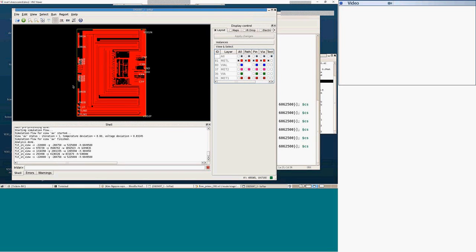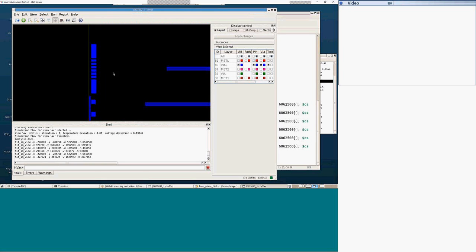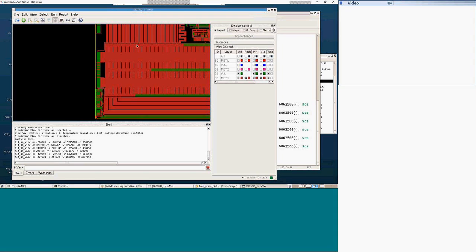So that's what we have, and this is GNDB. GNDB is fully disconnected, so this is a disconnected segment. It has only vias to metal 2. L2 is also disconnected, and it obviously has vias to metal 1. And the whole GNDB from here continues on metal 2, metal 1 only. So nothing on the top, it's a fully metal 1 connection.